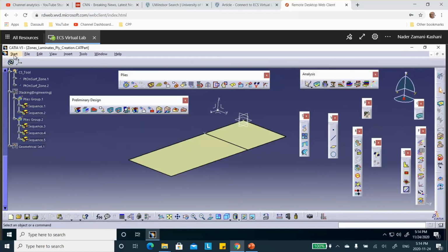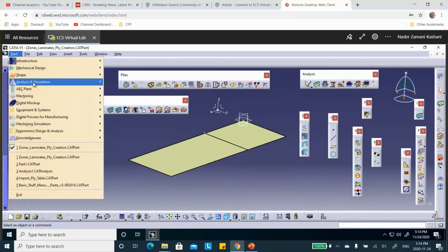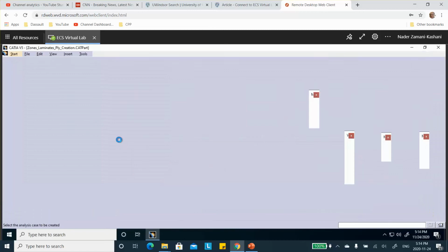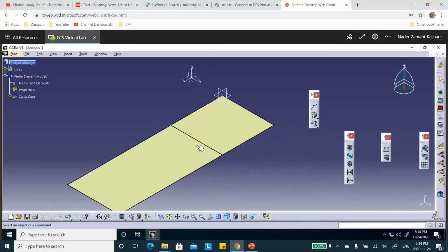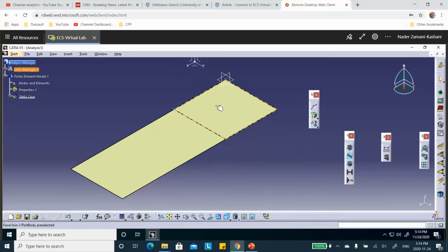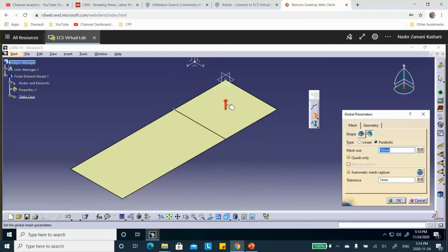We're going to go to the advanced meshing tool because I want to get a nice looking mesh. So first I'm going to mesh this guy with the surface mesher, and this is the surface that I'm going to mesh. Remember, we flipped the direction of the joint surface downward, so that this is going to be the direction of the normal to the shell elements. That's okay. So 10 millimeter.